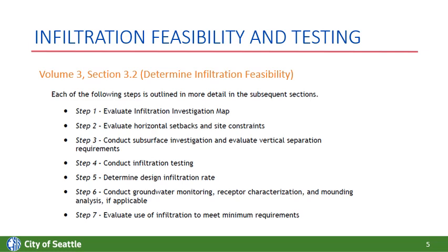So the design infiltration rate will be, for most projects, for small projects that are simple infiltration tests, the factor will be 0.5 from your measured rate to your design rate. So that's to account for different aspects of the infiltration rate over time.